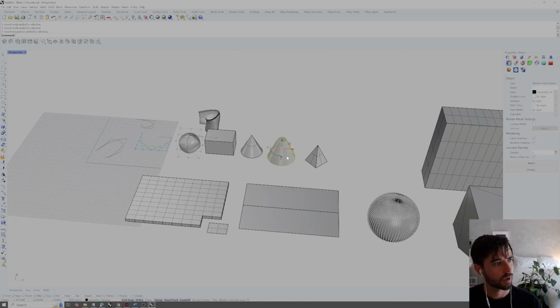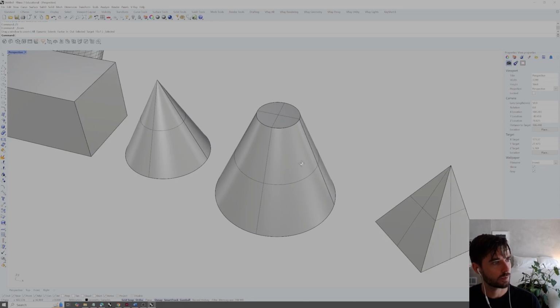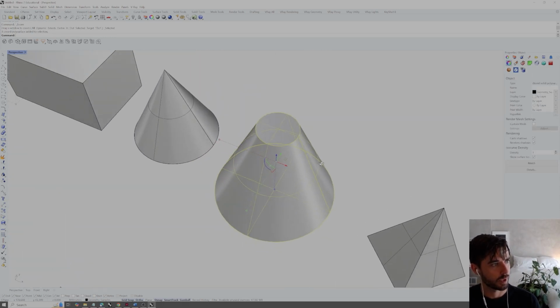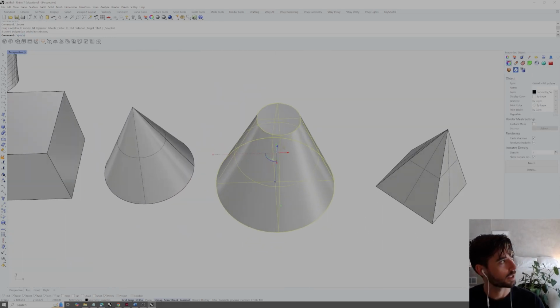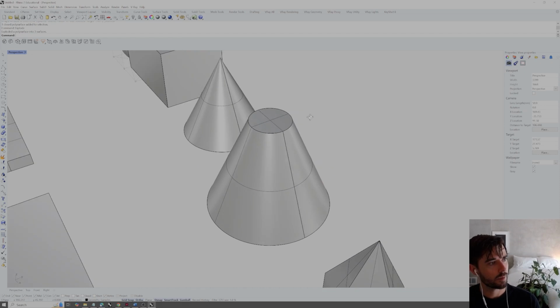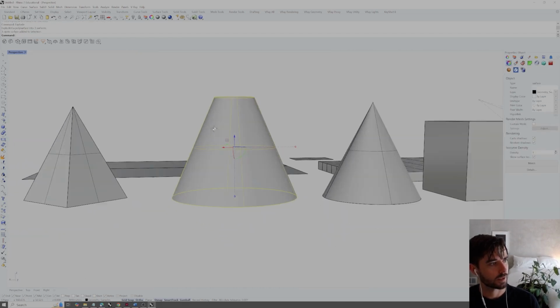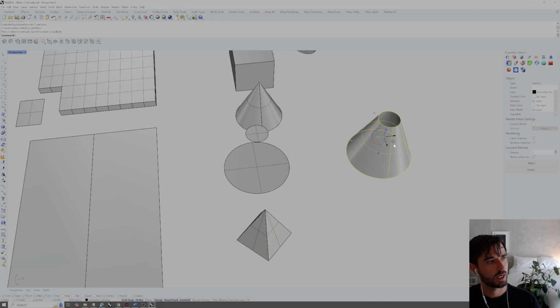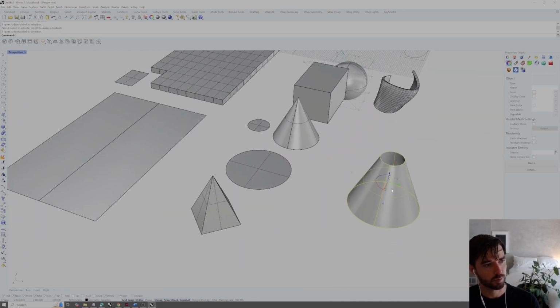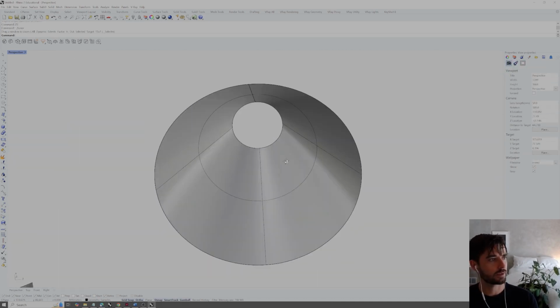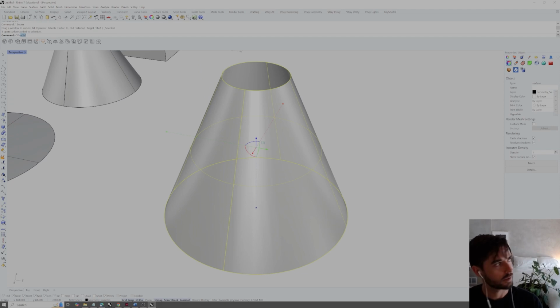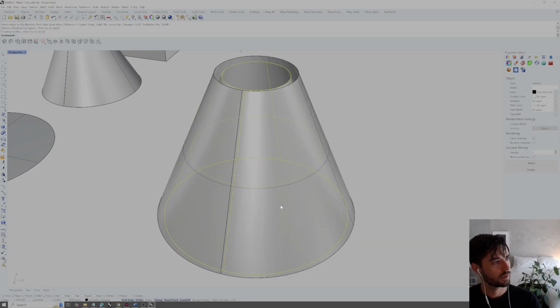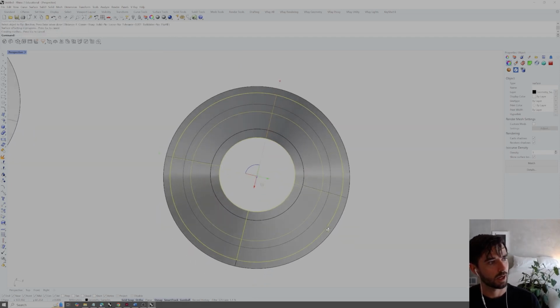We could also go into any of these NURBS geometries. So I'm just zooming into one of these. We could type explode to explode them. I could now select just this outer portion of the cone, so not the two top caps. Could move this over to the side to just prove it is a single surface with no thickness, and then type offset surface and offset this.